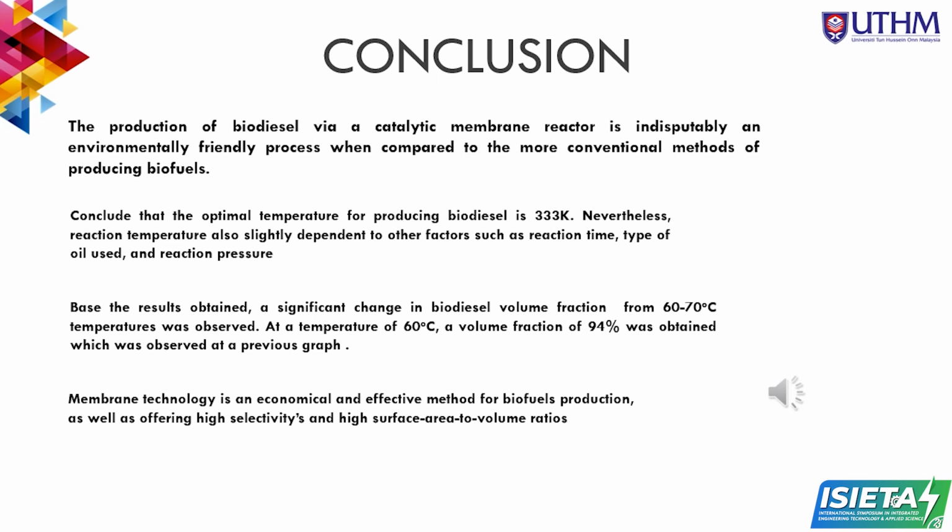Membrane reactors have encouraging chances for process intensification to enhance the methods used to produce alternative fuels. They eliminate the need for extra separation and recycling units by combining reaction and separation into a single unit. As a result, producing fuel uses less energy, also lowering capital expenses. In addition, compared to traditional reactors, membrane reactors can increase conversion and selectivity, eliminate mass transfer restrictions, and have stronger thermal stability.